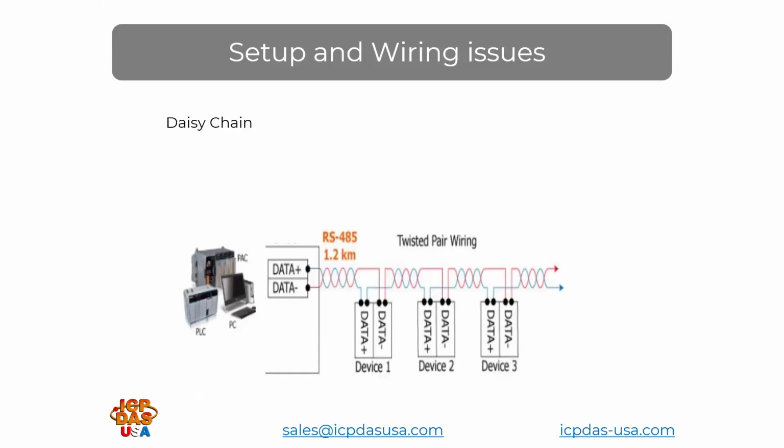Modbus RTU is traditionally communicated over an RS-485 network. RS-485 allows for daisy chain wiring schemes to be implemented along a single bus. The maximum theoretical distance of the entire bus is 4,000 feet or 1.2 kilometers. Note that I said theoretical. Baud rate, wire type, and number of nodes can significantly reduce this distance due to wire resistance, signal loss, and communication distance.